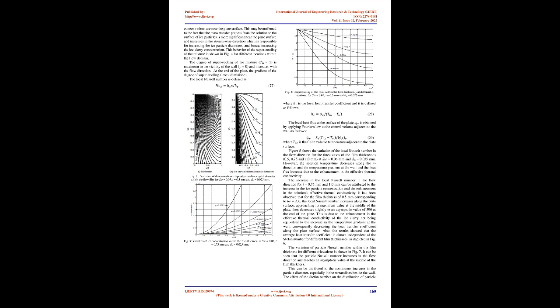criteria of 10⁶. The inlet flow at the top of the plate is assumed to contain a specified uniform number of ice crystals per unit volume of flow. The film thickness T in the Y direction is modeled as 0.5 mm, 0.75 mm, and 1 mm, and the plate length as 1.0 m. The concentration of the ice crystals at the inlet condition has been set at 4 × 10⁷, which corresponds to the inlet ice crystal diameter, din equals 0.025 mm, to initialize the calculations.